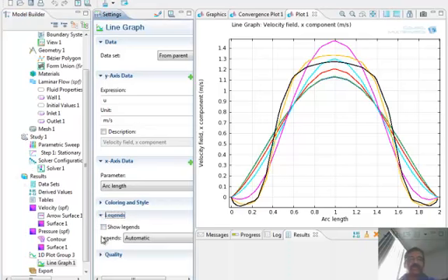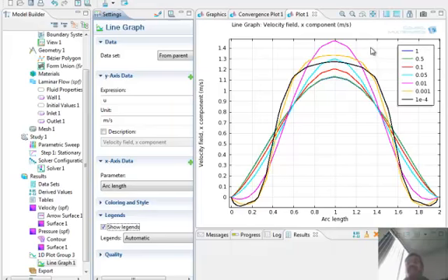So go to the legend, click the legend. Here it gives you the legend. So these are the viscosities. Okay, so it's basically each graph is a velocity variation of the x component for each Reynolds number. Okay, from 1 to a viscosity of 0.5, 0.1, etc. So what you notice here is the black one at the bottom, 10 to the minus 4, has a reverse flow. This is negative. In this region, and on the same thing on the other side, the flow is actually entering the channel, not exiting the channel.